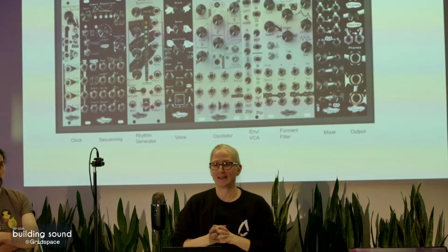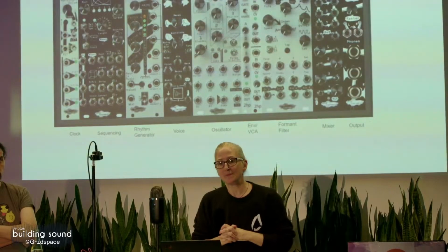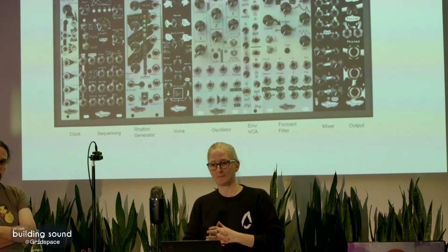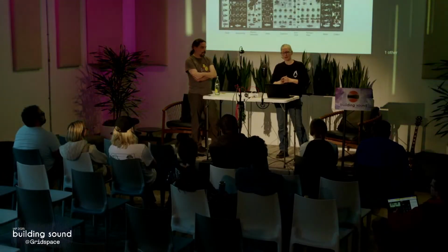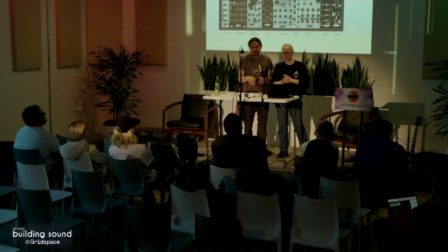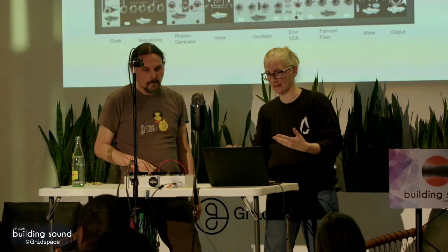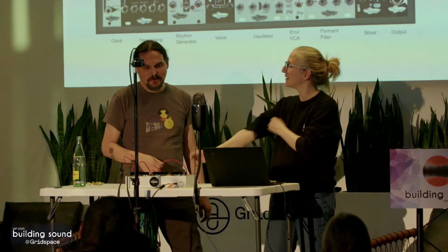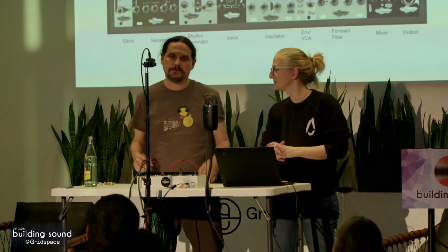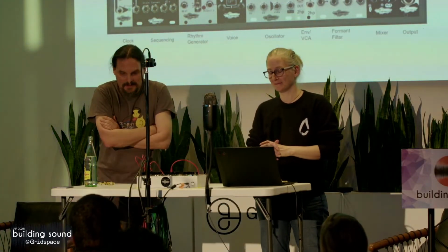Yes, question. For the clock, is there a limited number of modules that you could set the clock to because of the phase, or is there a module that you can use to extend connections? A kind of module that was not mentioned is called a mult. There's actually one built into this case, but you can split signals. The question was whether there's a limitation to how many clocks you can send out. Well, the clocking can get very complicated in modular because you can have modules that delay clocks, and so you can actually get all sorts of crazy complicated time skew too. So the clock tree in modular is sometimes problematic.